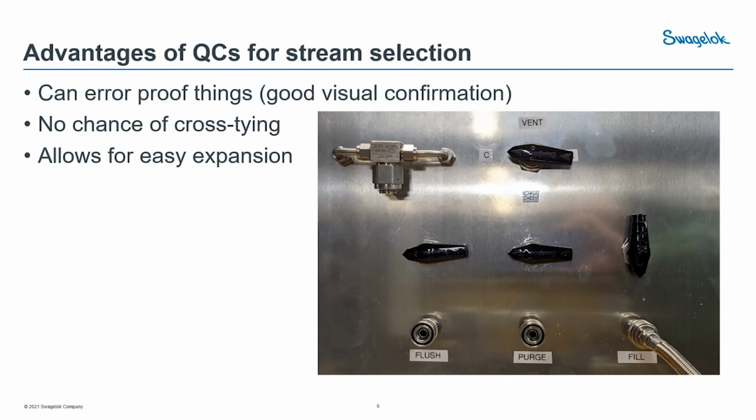Basically what they've got here, it's a little hard to see with this photo, is a 5-way valve at the top where they can select between product A, B, or C that they're going to load. They load into these little totes, or you can vent pressure off using that same 5-way valve that's connected to a plant vent. When they connect the tote, they're able to first flush the tote out to make sure it's clean with a clean fluid that they're using. I think it was water in this case. They then had a purge. That's to make sure all the flushing material gets out of there, so there's no dilution of the final product they're loading. Then they can plug into the fill line.